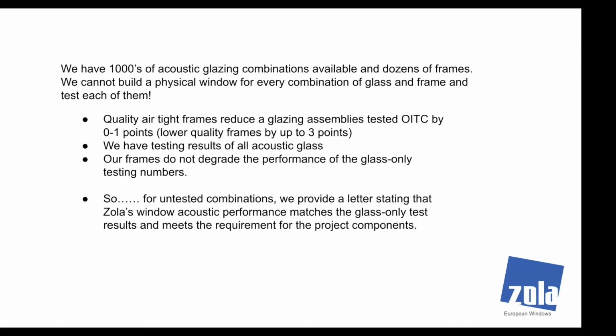But what we found is that quality frames don't reduce the glass's testing ability. We can actually say that if a glass has a 35 OITC, our higher performing frames will hold the glass's sound acoustics. When I say higher performing frames, I'm really talking about the woods, the thermoclads, the UPVCs, and the insulated thermoplast clads. When it comes to the aluminum windows, the insulated value is a little bit lower.